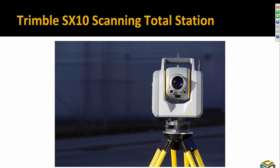It works right inside the same workflows inside of Access, so you don't have to learn a new piece of software to be able to use it. It works right inside of Access and then right inside of TBC as well. The highlight for me is that the point clouds that you shoot with it are referenced to any station setup or traversing that you've done with the total station. So everything comes into TBC already registered. You don't have to buy RealWorks to register your clouds. It's all based on your survey workflow already.